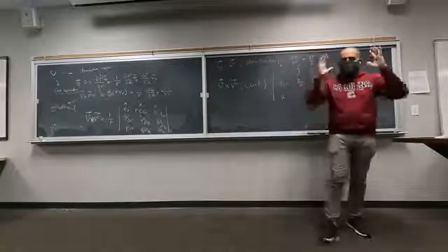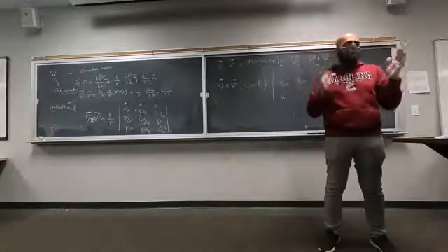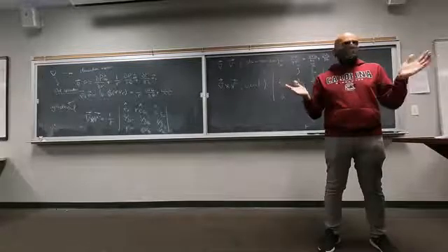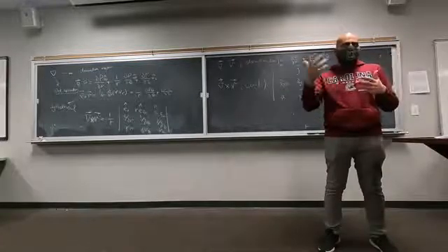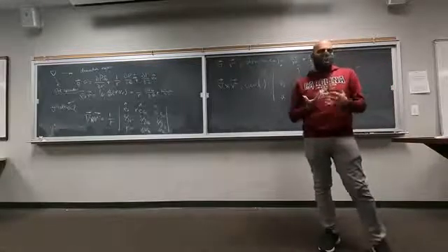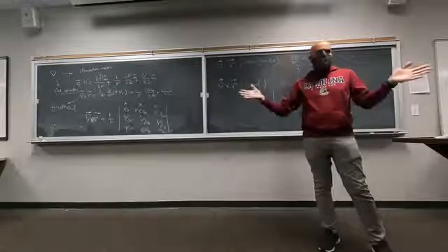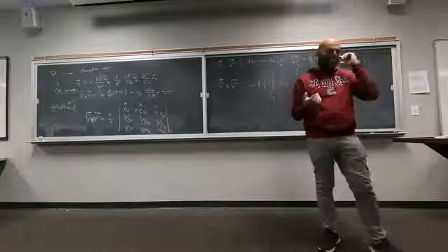It has to be an arbitrary volume in space. Write the equations for each side. The conservation may look very complicated, but it's actually pretty easy when you get a hang of it. Conservation of mass: m dot in, m dot out. That's it. There is nothing else to it.